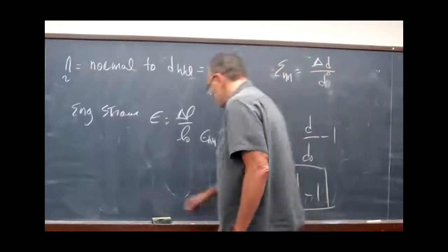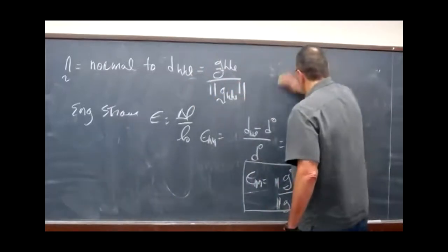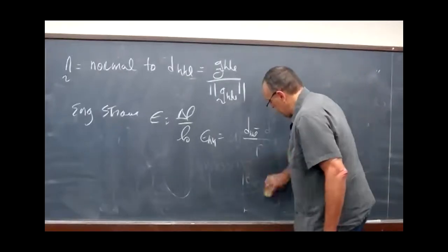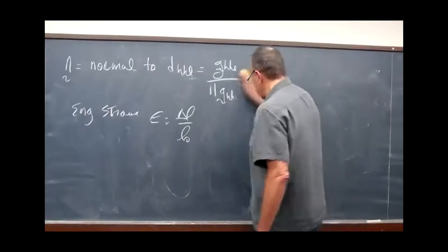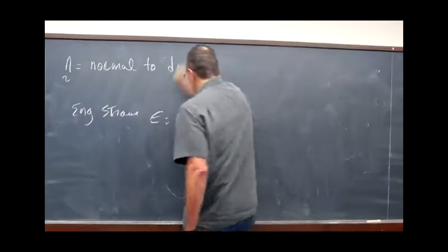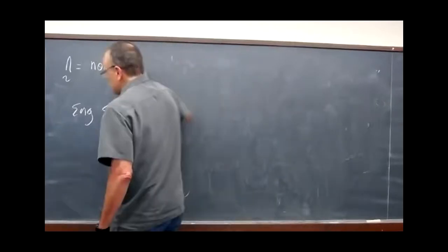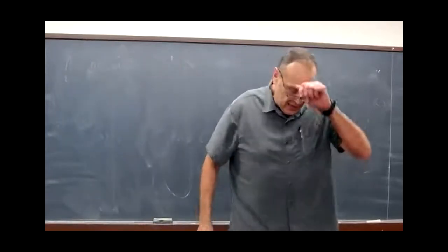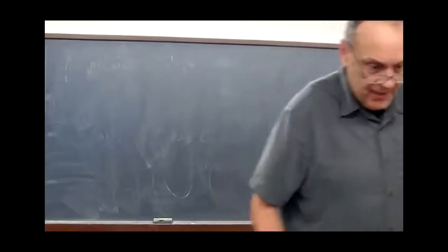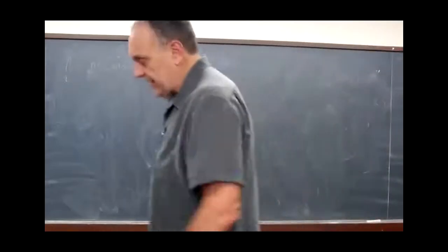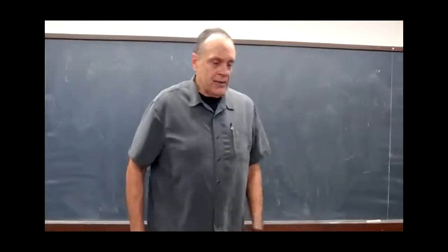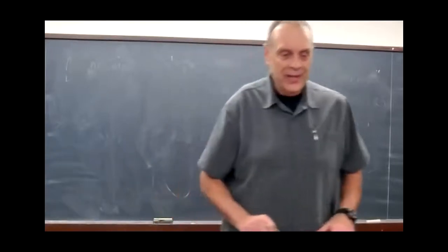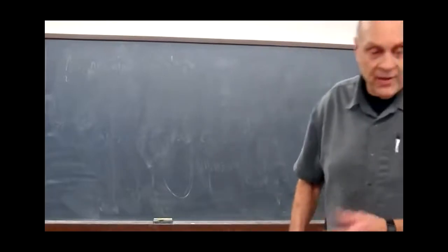I want you to appreciate that you can measure the lattice strain, and we'll talk in just a minute about how we know that lattice strain is actually elastic, because it's important that it is, because we're going to use it to calculate stress using Hooke's law. So we've calculated the lattice strain from our diffraction data. We have a data set. We've collected these images, and we go in and do the magic to find the spots and determine what those G vectors are, and now we can determine the strain.